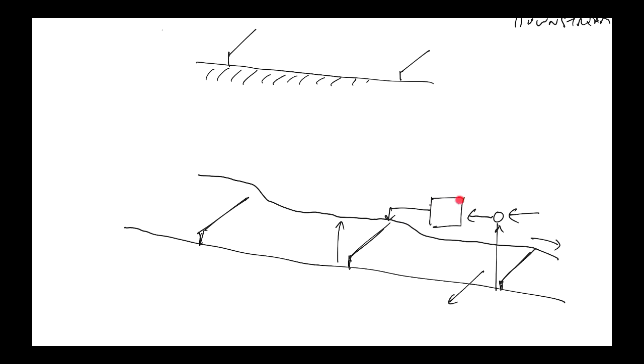And if that's done properly, in steady state the flow commanded by the controller for the upstream gate will reach a steady state value that matches the flow load. So that's the job of the controller. It's trying to adjust this to match the load flow. If this system reaches equilibrium, if the water level returns to the set point and stays there, it's telling you the net flow must be zero. And so the action of the controller ends up matching the flow over the upstream gate to the load flow.